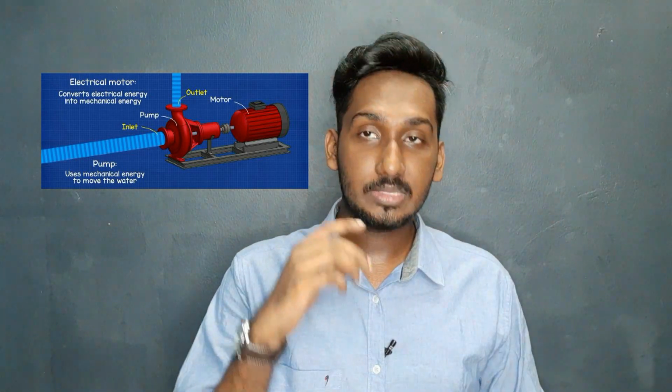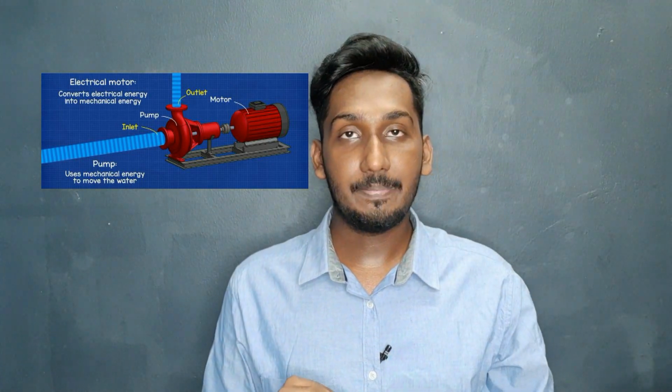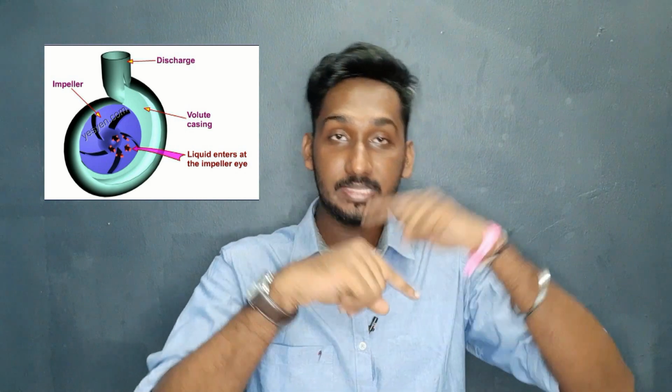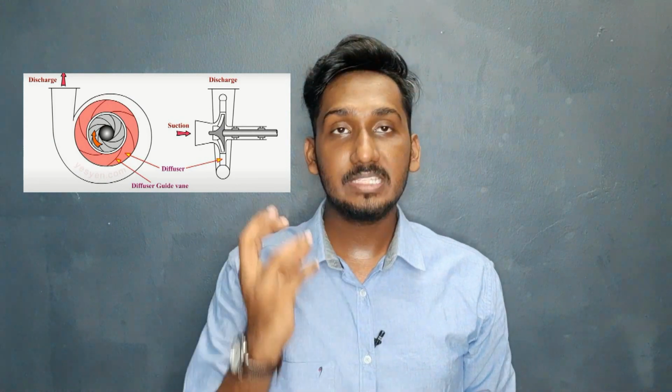After that, the rotating plates inside the pump will be distributed inside the cover, and then the water will be pumped out. Basically, the centrifugal force in the impeller will change the kinetic energy to the potential energy, which pumps out the liquid to the outside area. I'll explain step by step how it works. First, they let the hose inside the water to be sucked out, and then the water is sucked and goes into the impeller. Inside the impeller, the water will be rotated and then go out to the diffuser. What happens in the diffuser is the velocity energy which comes from the water from the rotation will change into a pressure energy so that it can pump out.